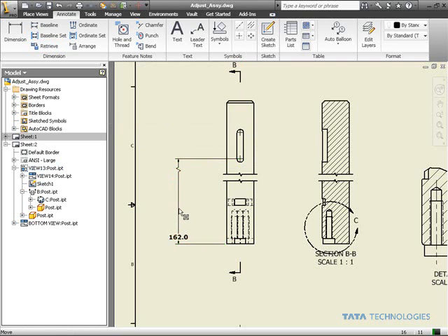This is an actual sketch dimension from our modeled sketch. We can clean this up by clicking on our view here and kind of bringing it in and out, and also drag it up, the value. That center line means that's the center of our dimension. And now we've placed a retrieved dimension, which is a sketch dimension, into our drawing view.